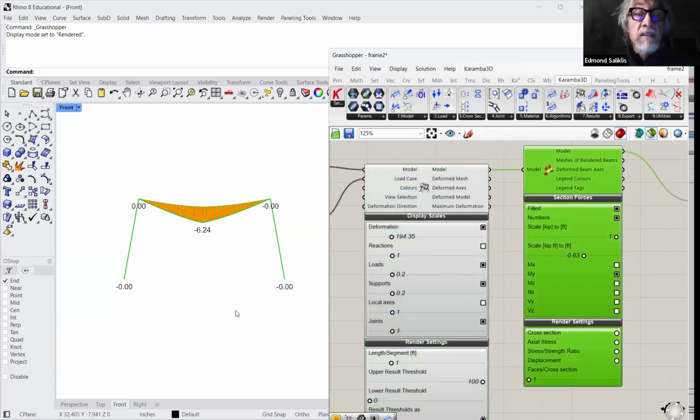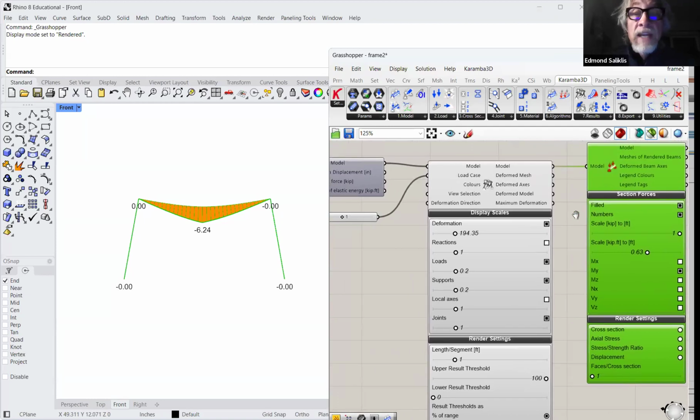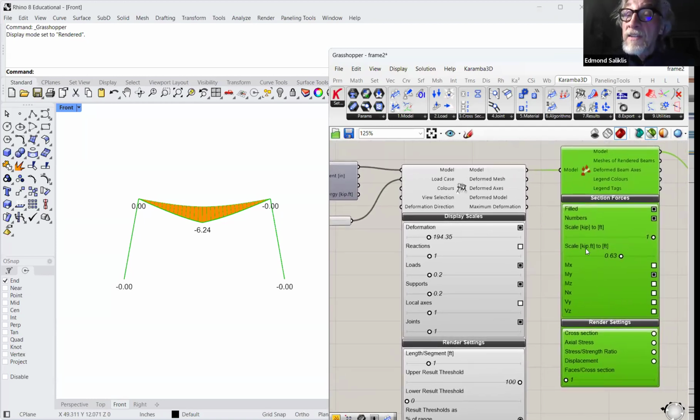Now let's take a look at the bending moment diagrams. And this, I think, again, is very telling, right? That for the roller pinned case, there is no bending in the columns. There can't be, because there's no horizontal reaction here. So there's no bending up that right side. And if there's no horizontal loads, then the horizontal reaction is 0 on the left-hand side.